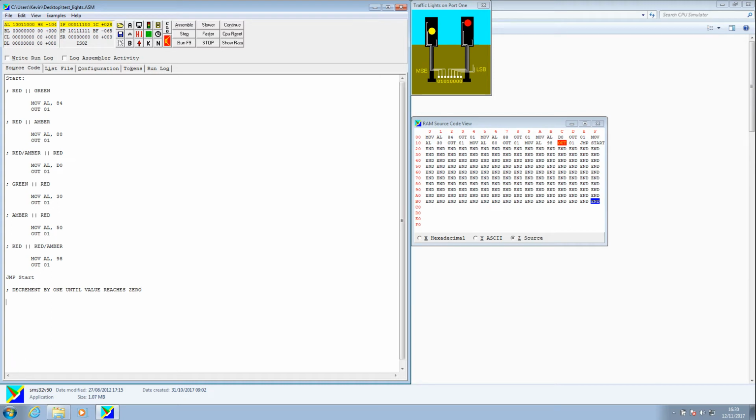We'll put this particular program up high in an unused memory area. So we've got, it starts at C0, D0, E0, F0, all the way across to FF, which is right on the other end here. This is all empty, so we'll stick it at F8. It's not a particularly big program, so it should fit in there at F8. To do that, we'll just do an org, and set it up so it runs at memory location F8 in the source code RAM.